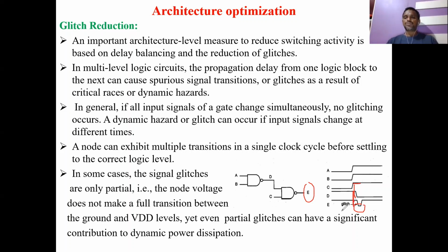The output we cannot reach properly, and at the same time it will take the previous output. It will take the previous input. So this D, which is generated from this NAND gate, will be late. At the starting point C will be obtained already, but here the delay will be there. Because of the delay, this gate will consider the previous input, whatever it may be. That's why you will get glitches here. So that is one point we have to consider: how these glitches are obtained.